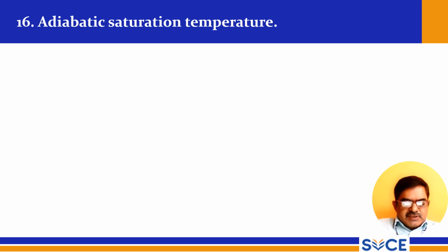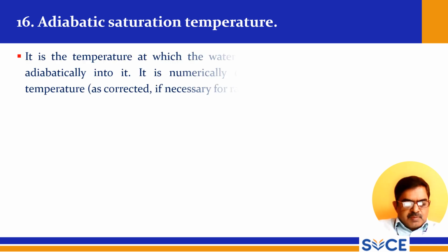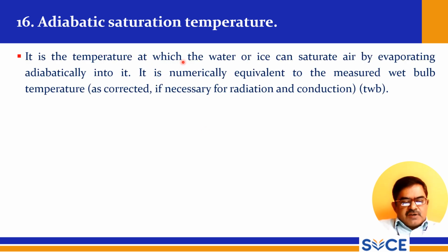Next is adiabatic saturation temperature, another very important term you should remember. It is the temperature at which water or ice can saturate air by evaporating adiabatically into it. It is numerically equivalent to the measured wet bulb temperature, corrected if necessary for radiation and conduction. That is the TWB.